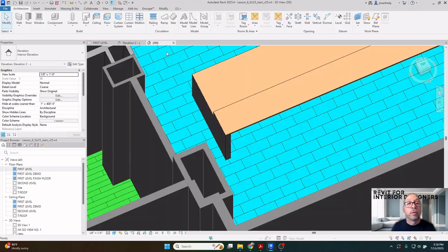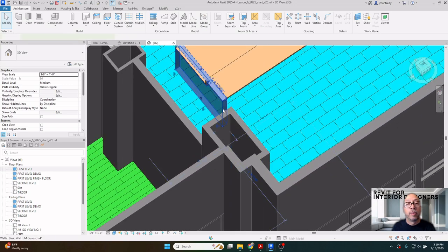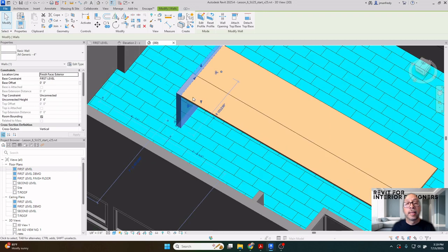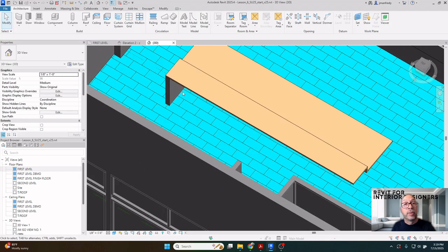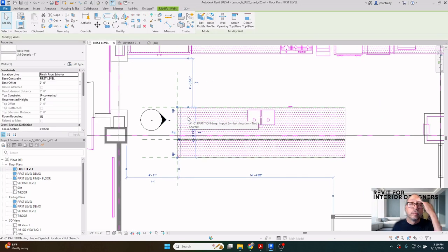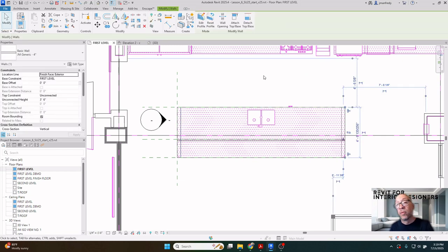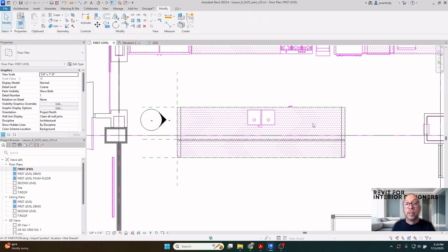Ignore that message for a second. Go to 3D. You'll see it there. So there's the wall. Later we can apply materials to it, but it's at the end of that countertop. I need that wall to be flipped to the opposite side. So in Plan View, I'll simply select it and use the Mirror command, and I will grab the center of this countertop here. If I scrub along the edge here, I'll eventually find the little triangle that denotes center, and I'll pick a point straight up, and I'll flip it over that imaginary line I drafted. It's on both sides now.